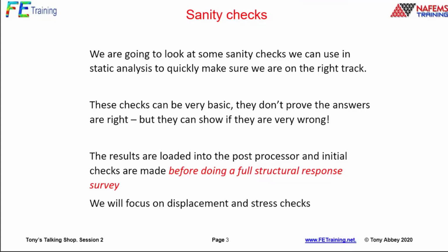So I'm going to focus here on checks which are really about displacement levels, if you like, and also stress levels. I've limited it to displacements and stress. Again, I do emphasize there are many, many more checks. We can talk about rounding error checks, load balance checks, all that kind of good stuff. Again, we can talk about that later on. I'm going to focus on this. So think of it like a 5-minute quick grab. Does this model make sense?